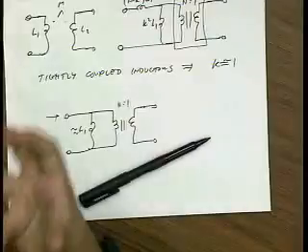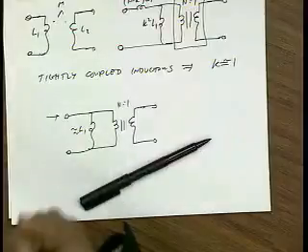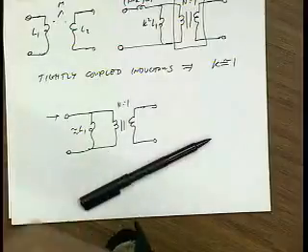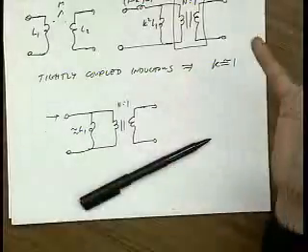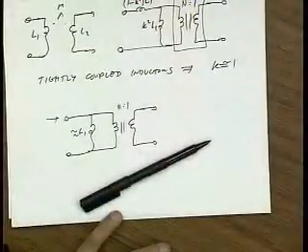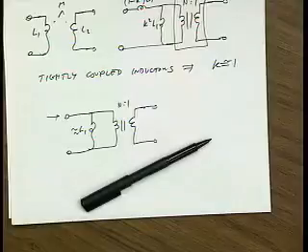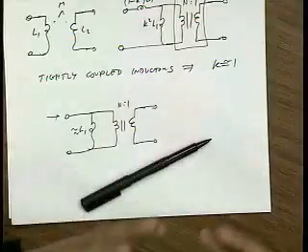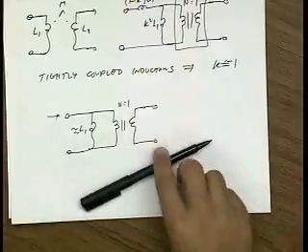You know, imagine lugging around one of these transformers in your suitcase for your laptop. The other problem with transformers, of course, is that the voltage is fixed. So if I'm on a 120 line, I have to use a different transformer than a 220 line. So if you traveled with a transformer, you needed to carry around 2 transformers with you. Nowadays, of course, we use switching power supplies, and so we don't have to worry about that. But that explains why the transformers were bulky, they're big, and they had the magnetic core, which made them heavy.